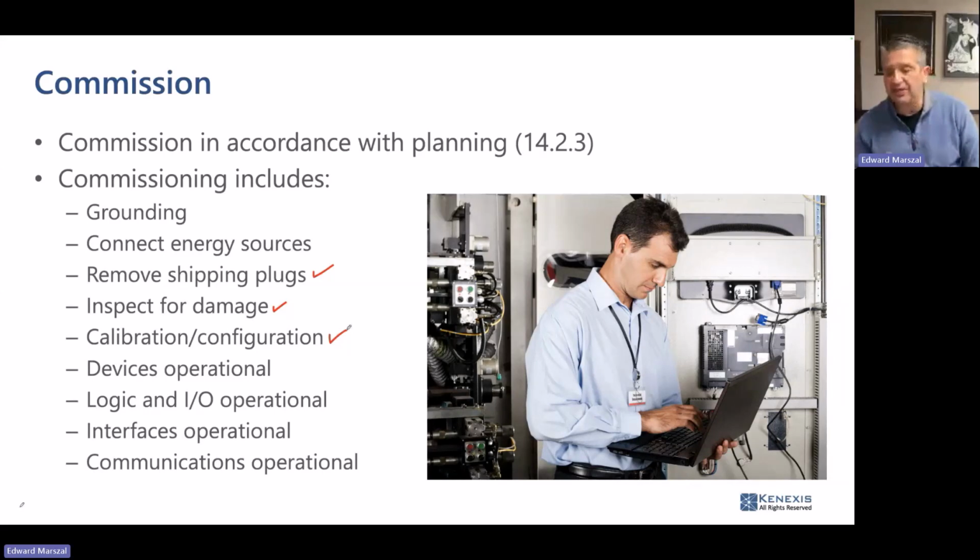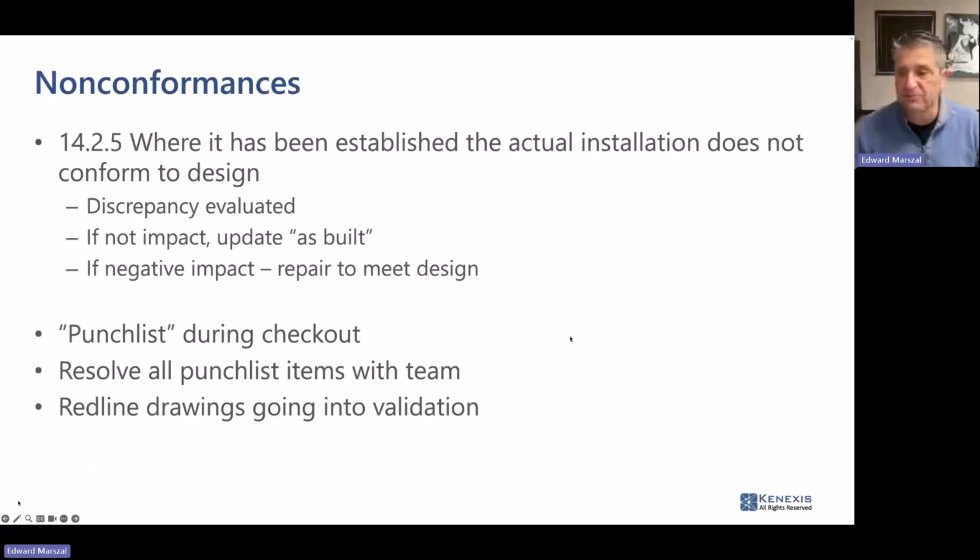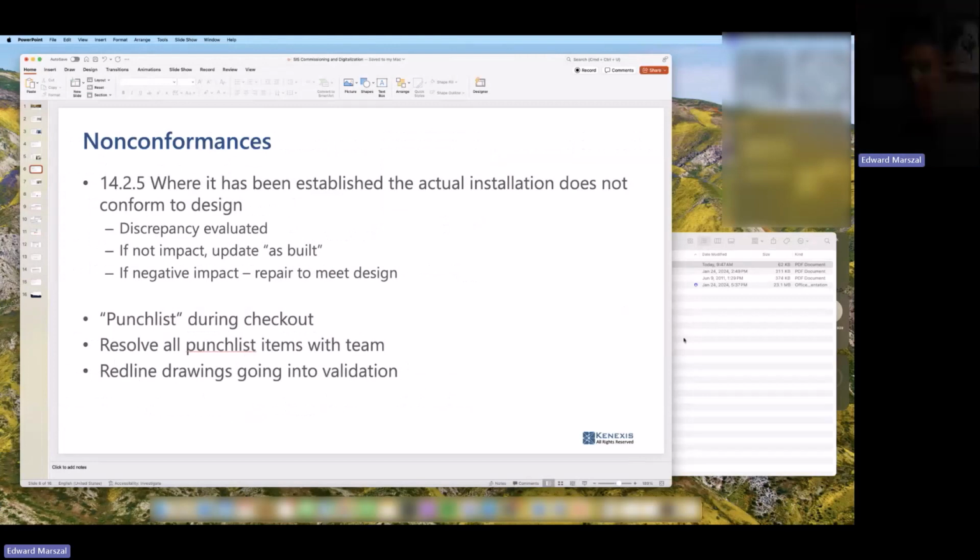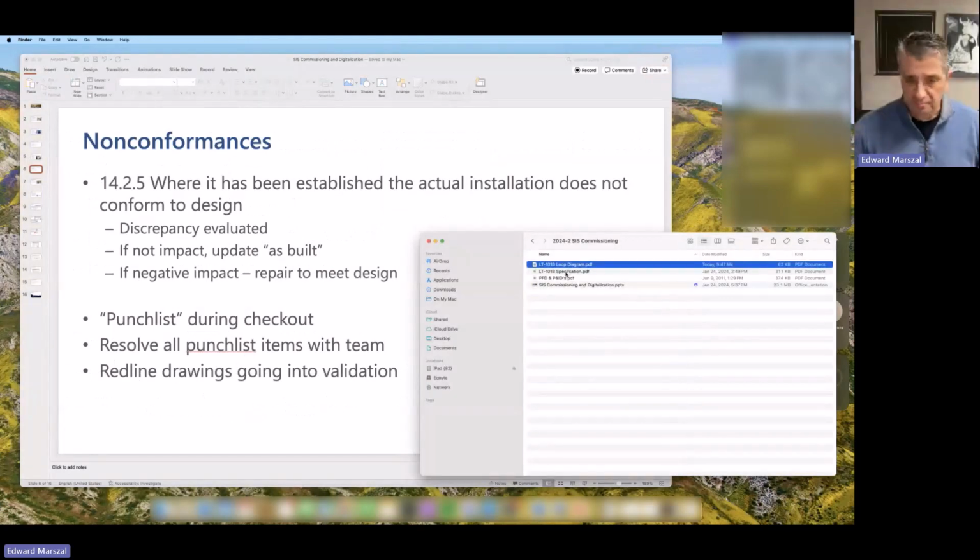And that calibration needs to be done in conformance with your spec sheets, and those spec sheets should match what's in the safety requirement specification.